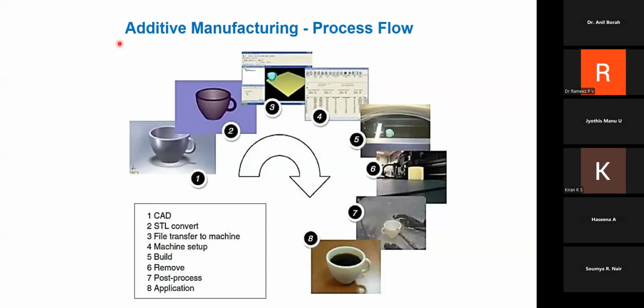So once you convert into an STL file format, you have to feed the STL file to the pre-processing software. But don't think that the STL conversion is a tedious process. This can be done in the CAD software itself. While saving your CAD file, there is a drop-down list.